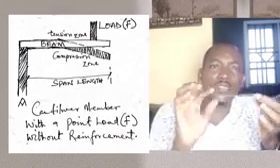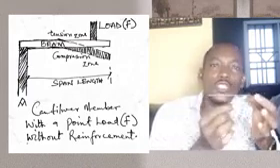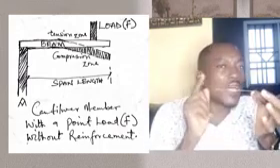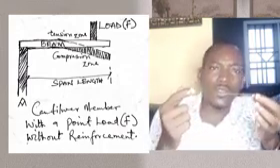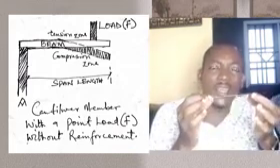So if you are at the site and you discover that you have a support condition like this and the area of concentration for rod is at the bottom, then you know that something is wrong somewhere. You can call the person in charge, if it's your iron bender or anybody, and advise as appropriate. This is another reason why it is always good for you to use an engineer at the site. Getting this area wrong, you might not see the mistake or the effect immediately, but your house, your construction work will not stand the test of time.